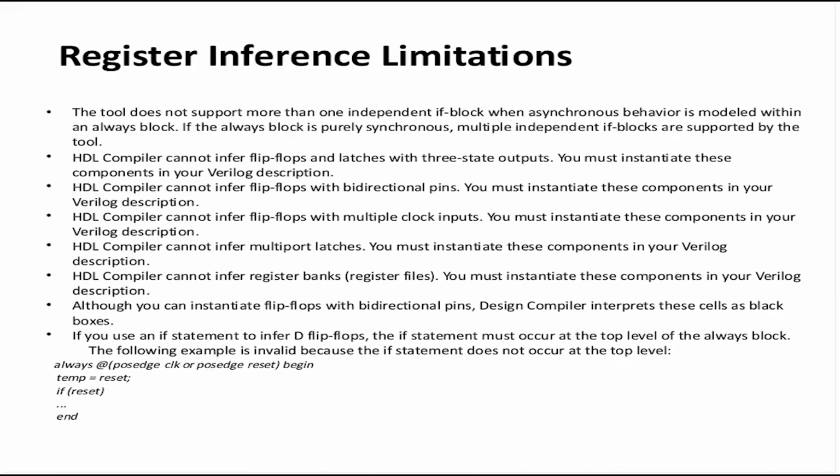Whenever we model asynchronous behavior using an if block, the tool does not support more than one independent if block when asynchronous behavior is modeled. If the always block is purely synchronous, multiple independent if blocks are supported. We'll see a few examples of this later.